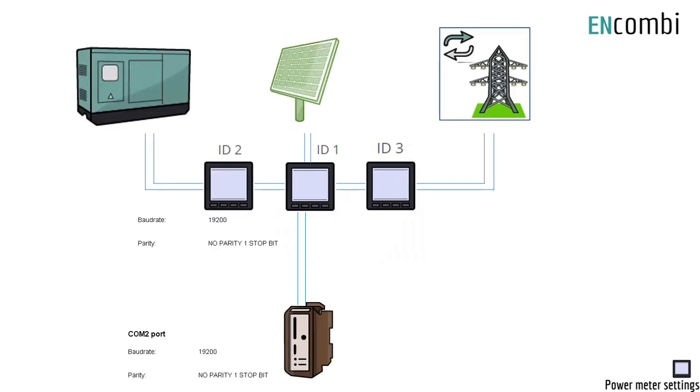Power meter readings will be used by the ECPv2 controller for the calculation and power references for the site control function. Power meter values can be read via Modbus RTU communication or Modbus TCP communication. The settings options have to be edited in the EC Web for both types of communication.